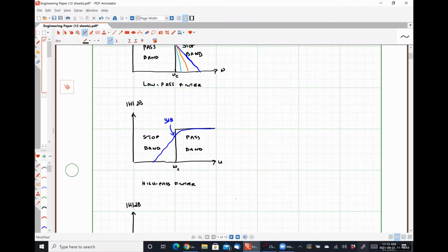So an amplifier, say your car's Sirius XM radio or whatever, has an amplifier that can take that very small, maybe millivolt or smaller signal and amplify it in such a way that it could be used to drive a speaker and you can hear it. So in that system, you might have a gain of 60 to 80 dB pretty easily.